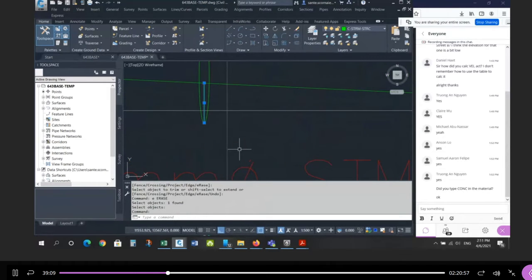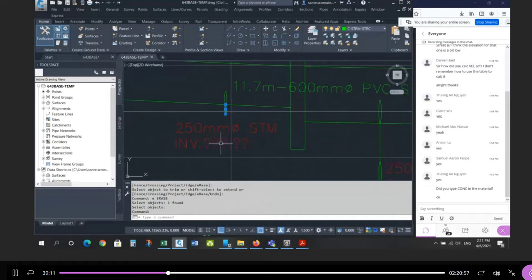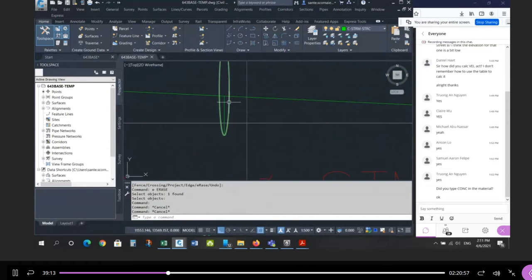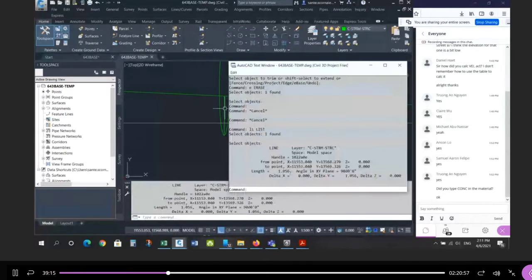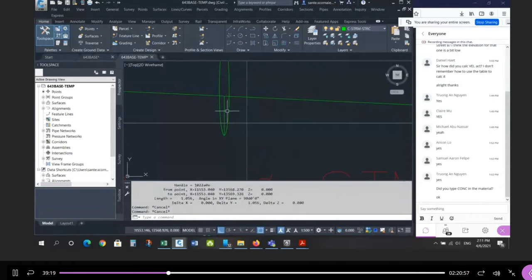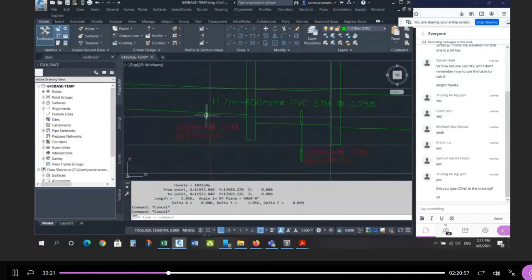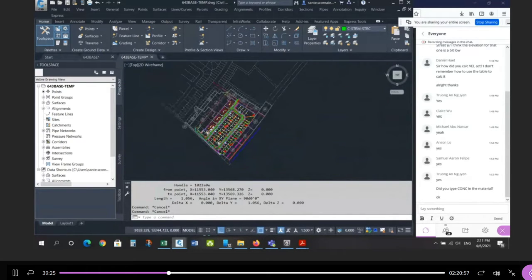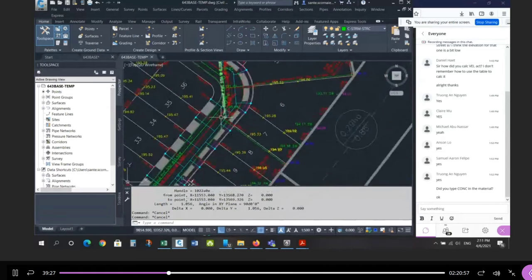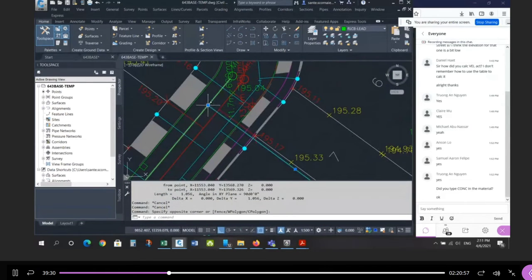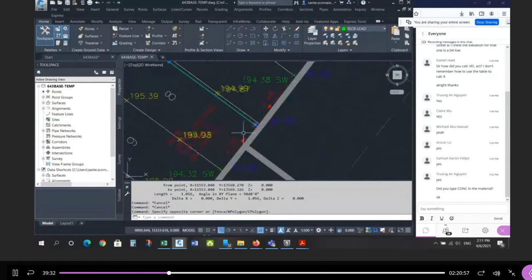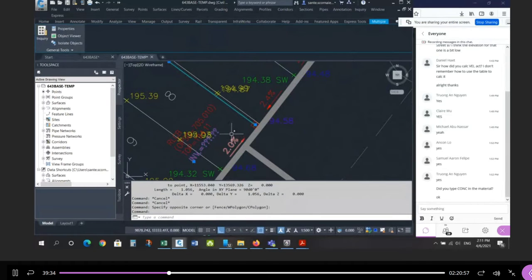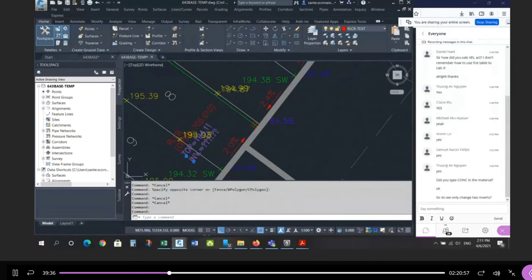So this is the vertical shift. You have to raise this invert, whatever you calculated, by this much. And remember, whenever you list this, you have to divide by 10. So it's only 0.105, about 4 inches. So these two need to be adjusted that way. Recalculate the invert here, and then work backwards. You know the new elevation at the street, at this end, go up at 0.5% and recalculate the invert here. And you'll know the difference between this number and this number does not have enough cover.